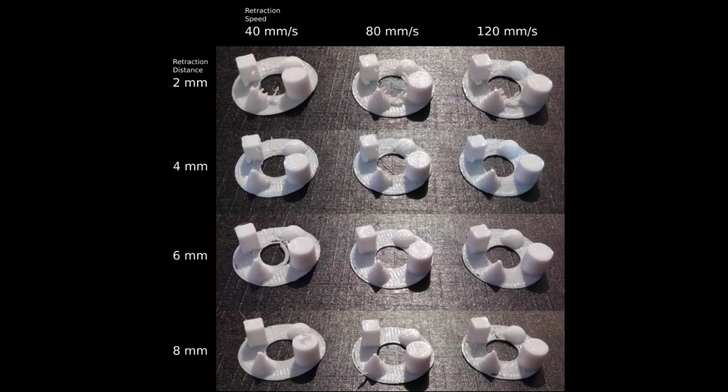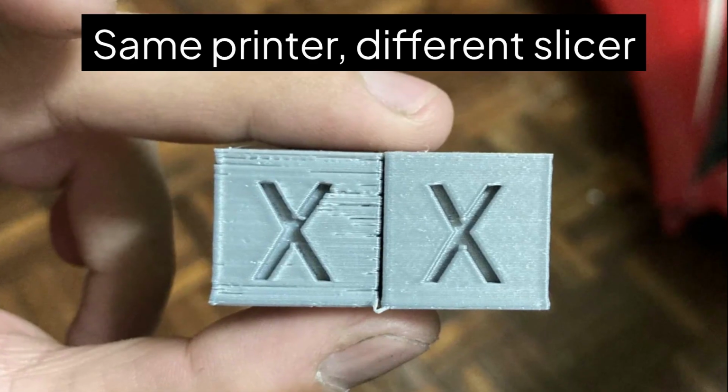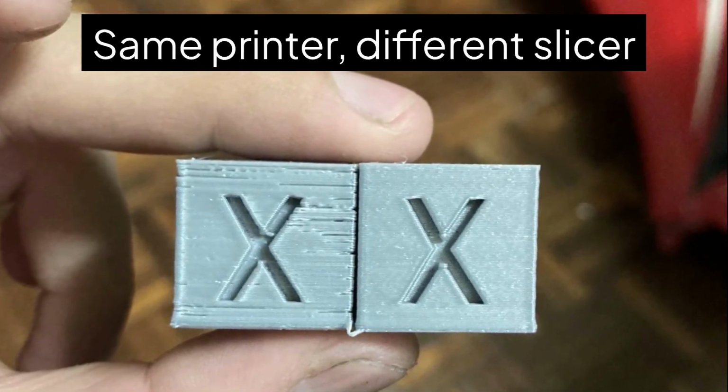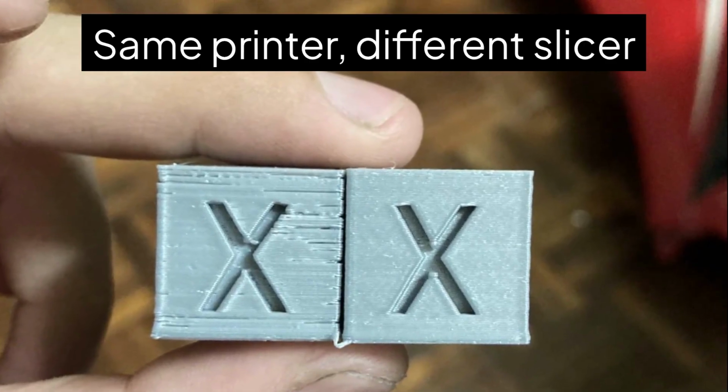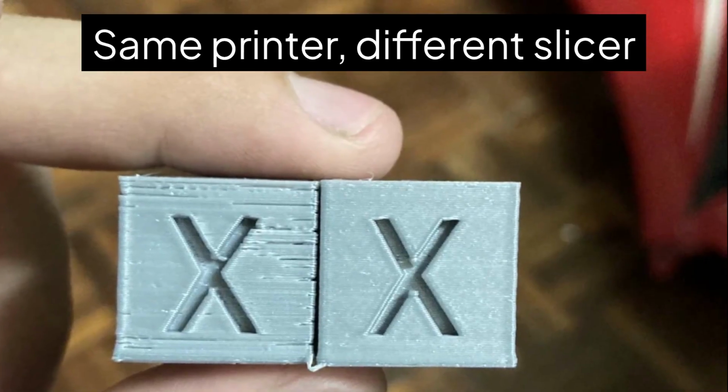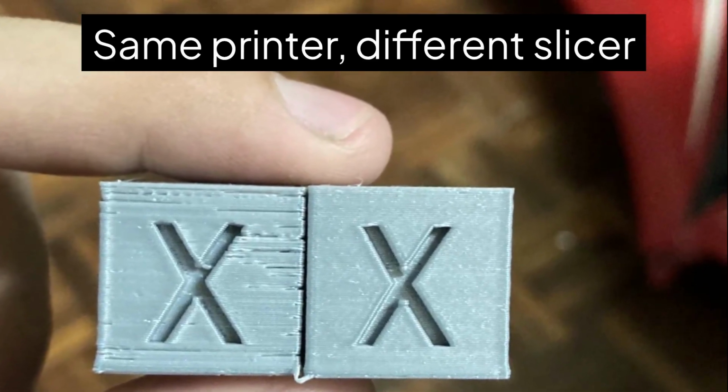The slicer also has to manage retractions. Whenever the print head moves without printing, the slicer decides whether to retract filament. That decision is based on distance, speed, and context. Too few retractions and you get stringing. Too many and you grind filament, introduce delays, and increase wear. What's important here is that retraction is not a property of the printer alone. It's a choreography between slicer decisions and hardware behavior. Two slicers with identical retraction settings can behave differently because they plan travel moves differently.